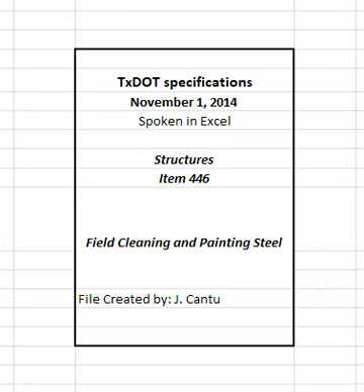Cure the primer, when System 1I is specified, in accordance with Table 1 before applying appearance coat. Table 1. System 2 Primer Cure Times. See Table in Specifications. Clean coated surfaces by an approved method that does not damage the paint to remove all dirt, grease, concrete, overspray, and any other substance that may impair adhesion before the application of the next coat. Provide an even and uniform appearance throughout the painted portion of the structure.